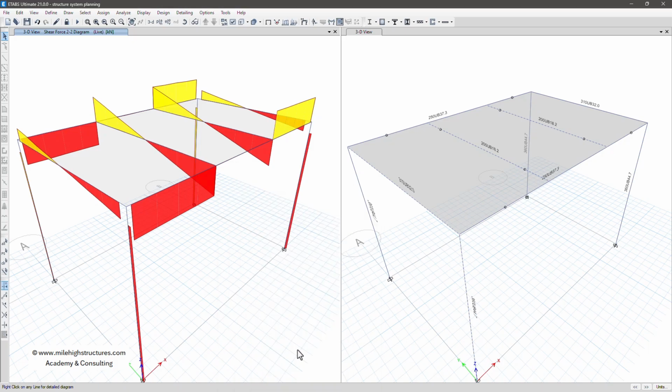So I hope the concept is clear to you, and as I said, this beam always has to be simply supported because it is connected to the steel beam, which does not have any capacity to balance the moment. If any engineer is allowing the moment here, he or she is doing wrong. It is always recommended that one frame should be a moment frame and the second frame should be a shear connected frame. So this frame that we have selected here is the shear frame, and this frame here is the moment frame.